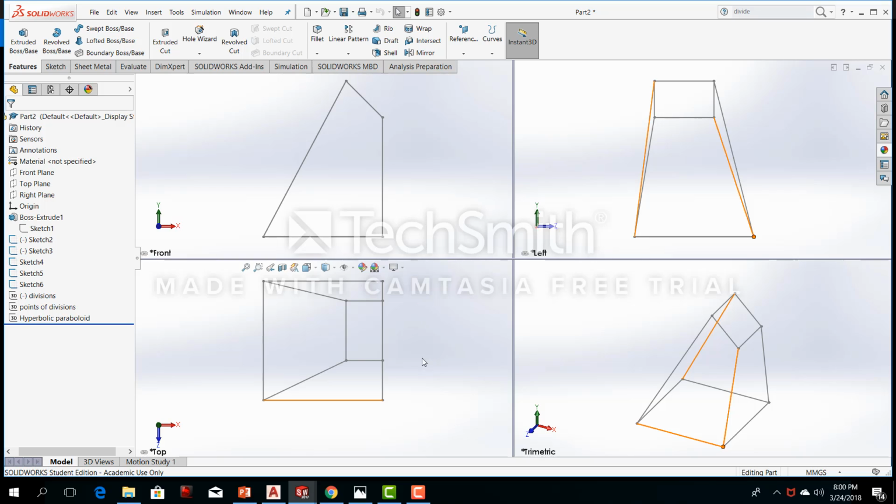Now this can't be correct, and it's very simple to see why. If we treat this as a singly ruled surface, we'd be doing it like a regular orthographic view. We'd take this point here on our corner, bring it across to our end view, drop it down for our plan, and it would have been down here somewhere along the surface, joined back up. It would have been down at an angle along here, and we could have said then that was correct. However, it's not. So what we can say from this is that it's a hyperbolic paraboloid because we're given a surface stretched between two skew lines.